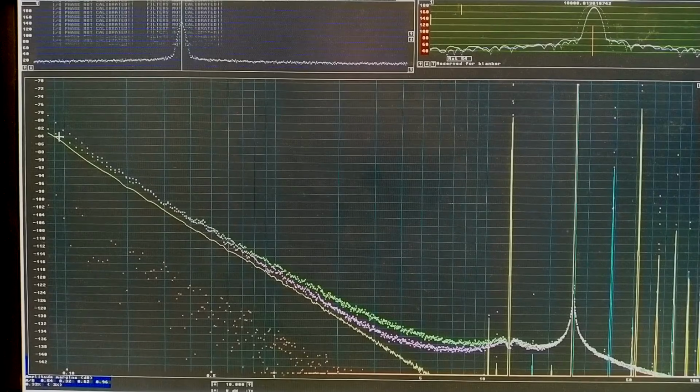This means that the Wenzel is significantly better than my current experimental oscillator. The difference is only 1 decibel. When the difference is 3 decibels, the noise is the same from both oscillators. It's like here at 0.2 Hertz or 0.25 Hertz, there is about 3 decibels to both oscillators.